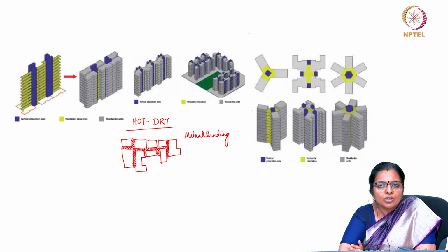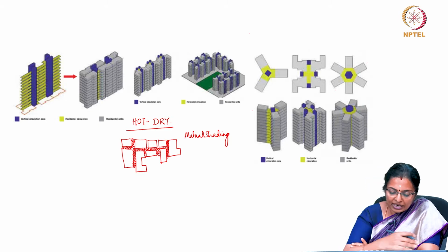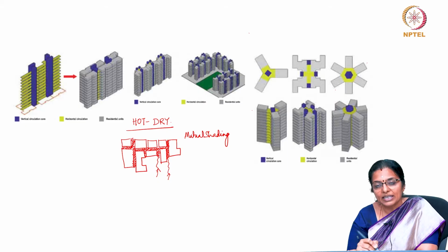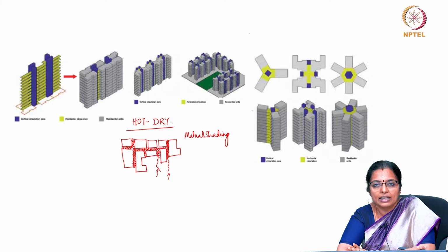Group buildings close to each other, especially east and west walls, should be placed close to each other for mutual shading, and we should promote access to cooling winds. If there is a wind direction, then we must promote this wind, because it will get promoted because of the channel effect or tunnel effect.